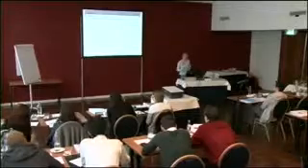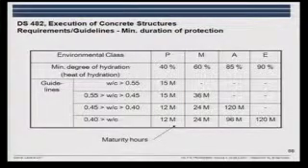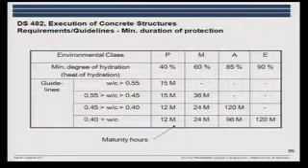Then the next example, some considerations we could look at is that when you're casting concrete, there are guidelines as to for how long you have to protect the concrete. You protect it so that the water will not evaporate, to ensure that you have a sufficient hydration of your sample before the concrete may leave. And this is an example from the Danish standard. It's an execution standard, and now it's overtaken by the European standard. But the example can be used.